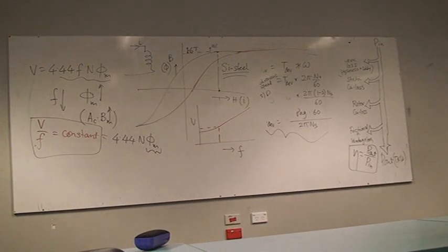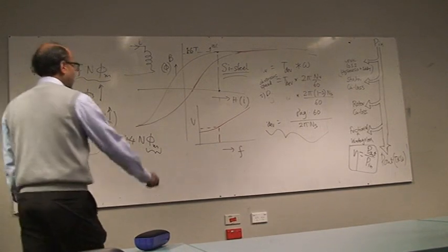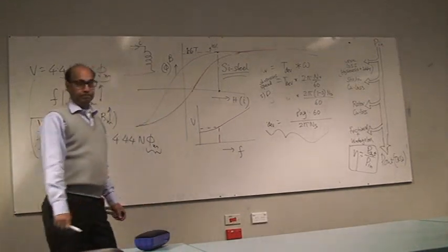So there's a minimum running speed. Yeah, you have to have a minimum. There is some power which you need to overcome, stator copper loss, rotational losses. So your voltage should be slightly high at low frequency.